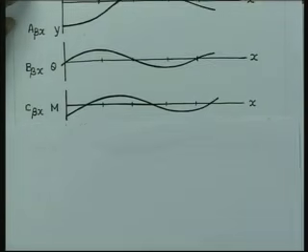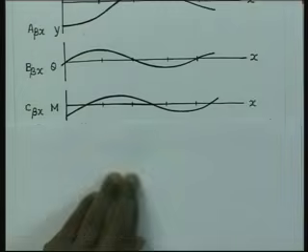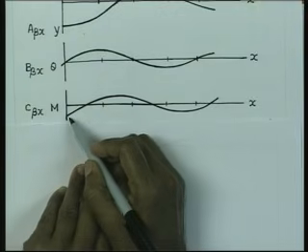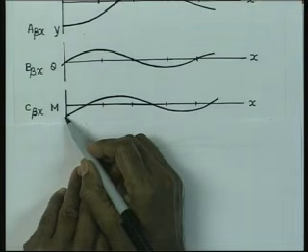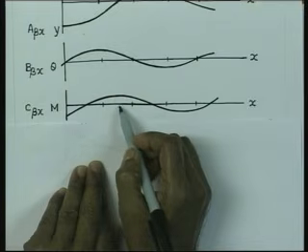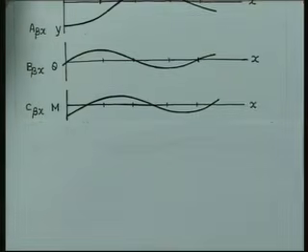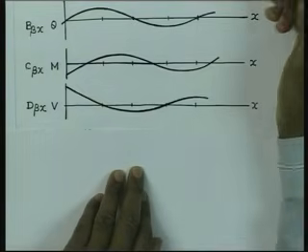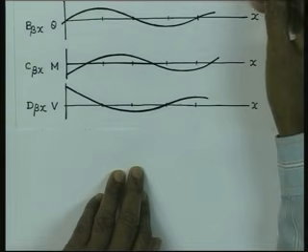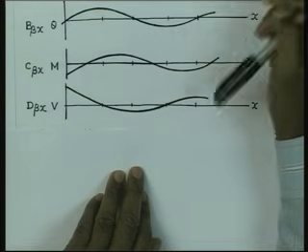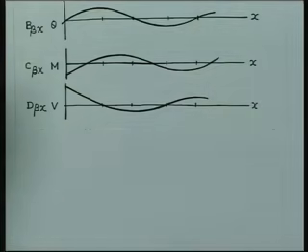And variation of bending moment is like this. Here it is a symmetric function, it has some amplitude there and again it changes. Likewise, the variation of the shear force is anti-symmetric and this is how it varies. So, you find that one function is symmetric, the next derivative is anti-symmetric and it goes on. So, that oscillation takes place.